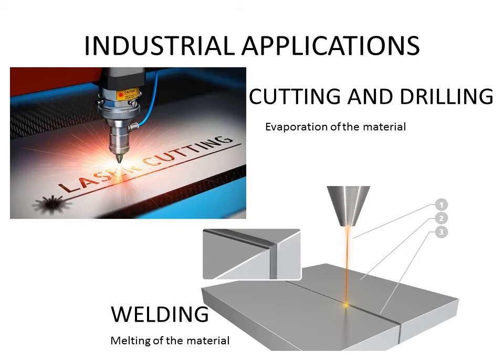Also the Nd:YAG laser is used. That is another infrared laser, operating at a wavelength of 1.06 micrometer. So normally for processing all these materials, whether metal, brick or cement, it is the infrared laser which is normally used.